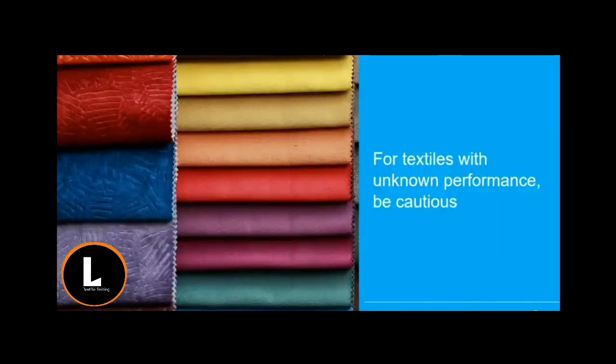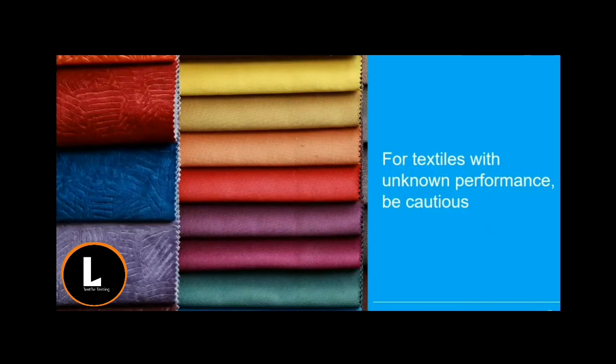If it is the first test of a fabric with an unknown fade grade, it is better to proceed with caution and start by putting the test on for short assessment intervals. Try 1 hour at first and increase in small time intervals, as you don't want to overshoot the mark and fading of the specimens, because this can ruin the test and it can also waste many hours of testing that you've already put in.